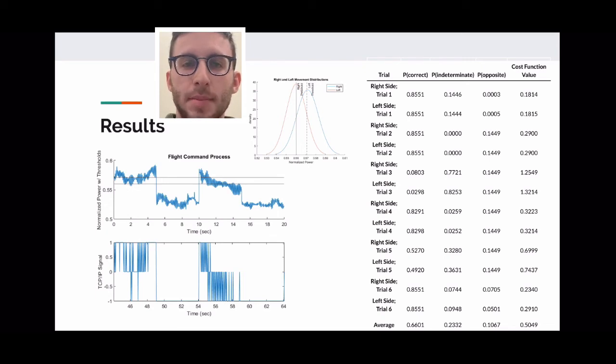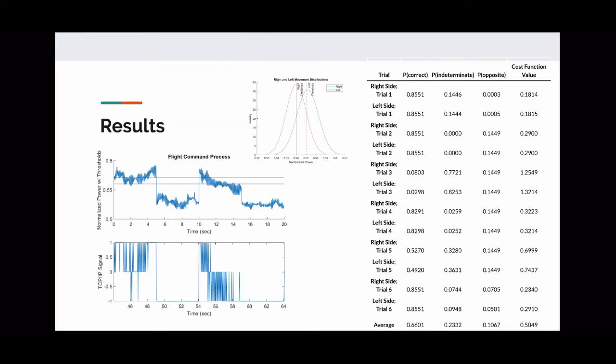Because of issues with Simulink crashing during live streaming due to the LSL inlet failing, the control inputs were not done in real time. In addition, the EEG data transmitter began to crash the data streaming software right before the final test flight was about to take place. To get around this, we use data from one of the trials, and the commands over time are shown on the left side. This data was fed into Simulink from the MATLAB workspace instead of being fed in real time through the LSL inlet block. The following video shows this resulting test flight.